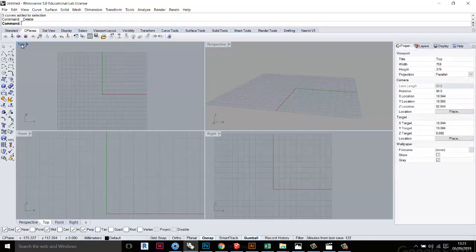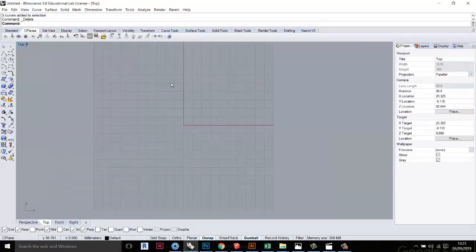Let's look at orthogonal next. Orthogonal is quite nice and quick. If I start a line, I'm going to hit 0, enter to get it to go from the midpoint. At the moment I can input any angle for the next click. If I hold shift, notice that this ortho comes on here. That means orthogonal, and that locks you to specific angles.